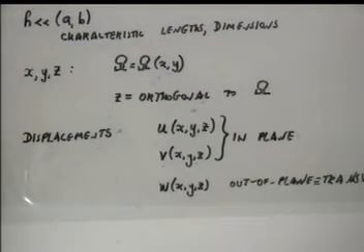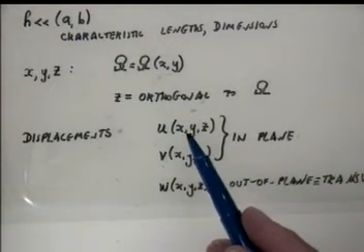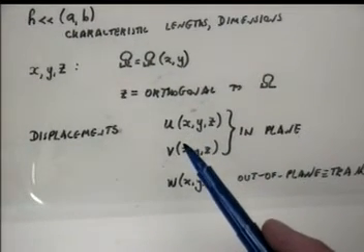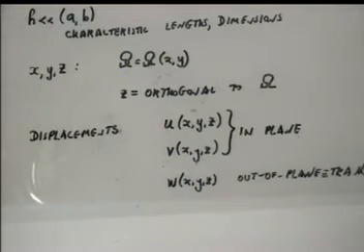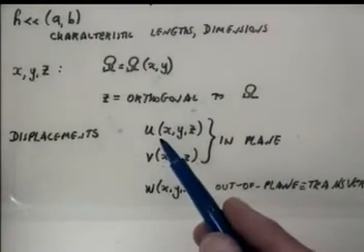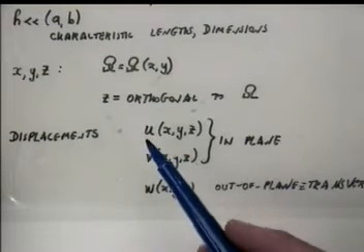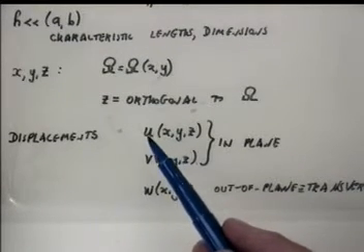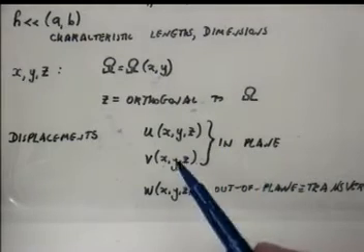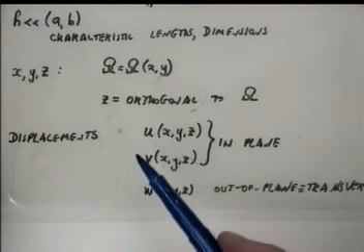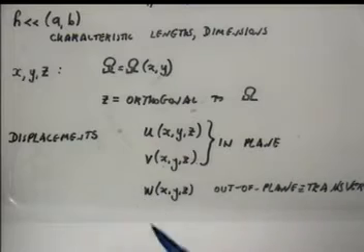Now displacements, now what is displacements? If we take a point, any point, in the plate, so this point can be on the middle surface or it could be just inside the thickness, anywhere. This point undergoes some displacements, and displacements are u in x direction, v in y direction, and w in z direction. There are 3 displacements.